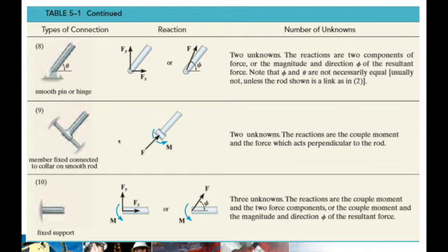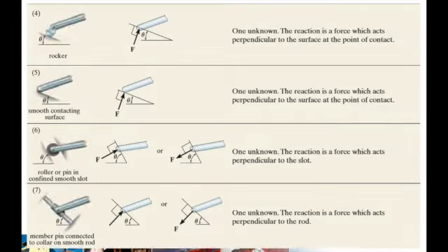Okay, so either you memorize all of that or you just try to remember the two general rules for establishing support reactions. That is, if they prevent translation and if they prevent rotation in a certain direction, then it means there is a support reaction there. This is the first step in drawing our free body diagram, and we will be doing a lot of this in our next lesson, which is about structural analysis. So you need to familiarize yourself with these types of support reactions.